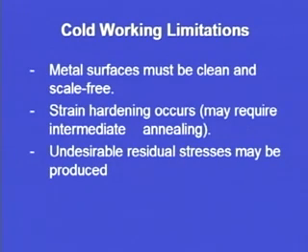Then undesirable residual stresses may be produced. Now, these residual stresses that are produced during the process of cold working may later on affect the in-service performance of the product. So, these residual stresses sometimes may result in a failure of a material or the product that has been made using the cold working operations.